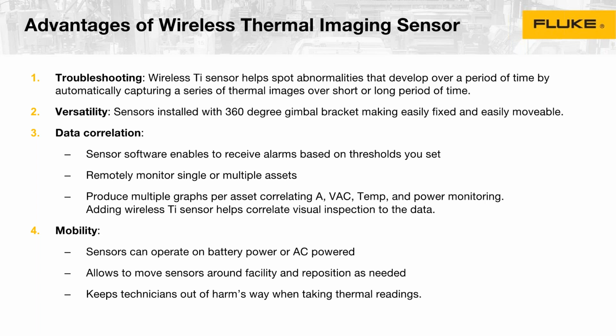It was clear for me, especially when I was a field service engineer for many years, that multiple parameters are a really great indicator and will reinforce whether you need to take action on a piece of equipment or on a process that needs to be changed. So once you get an alarm, you can remotely monitor the assets, looking at the AC, DC, temperature, power monitoring, along with the vibration and your thermal. That often will give you a complete picture of what you need to do if there's something to do, or if the application or process works well. And obviously,